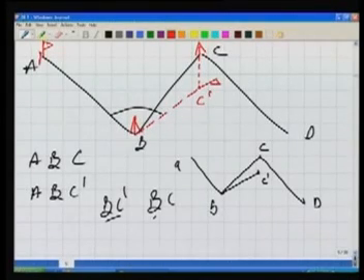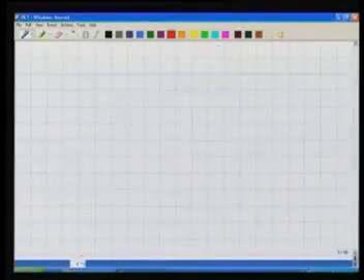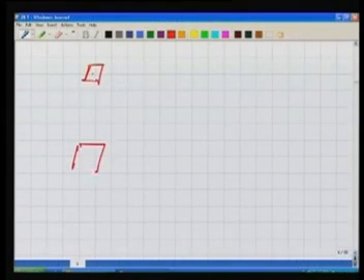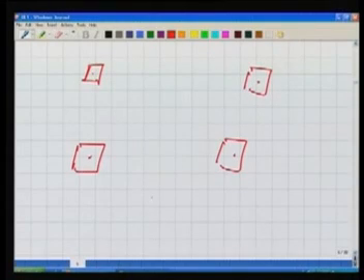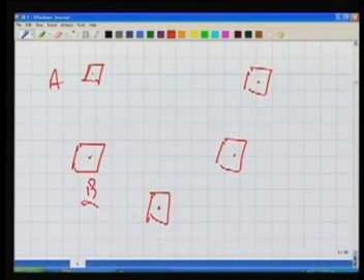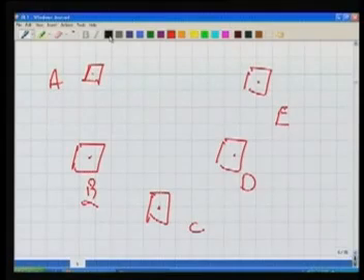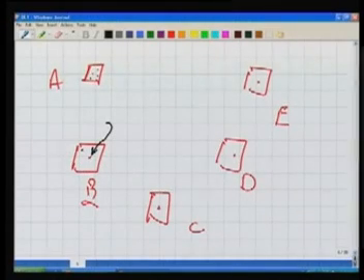Now how are these points marked in the ground? Why do we take our theodolite to C, not to C dash? These points are marked in the ground by some blocks, the way the stations are marked. So there in the ground A, B, C, D, E are marked like that. Now what is miscentering? Miscentering means we want to center our instrument or ranging rod at this point, but we are doing it somewhere here or here or here. Now let us say the miscentering for the ranging rod was this, but next time when I bring my theodolite, I put my theodolite at this point, because naturally the desire will be to center it correctly. So the theodolite is centered correctly, but the ranging rod was centered wrongly.